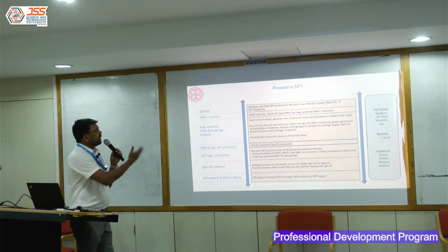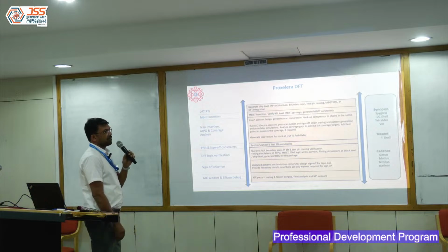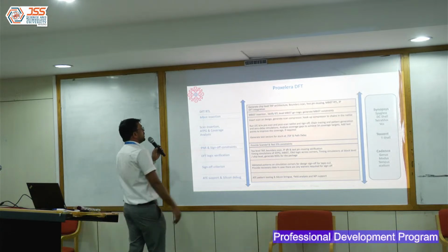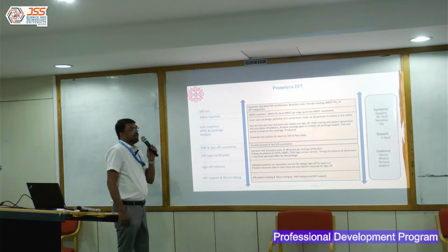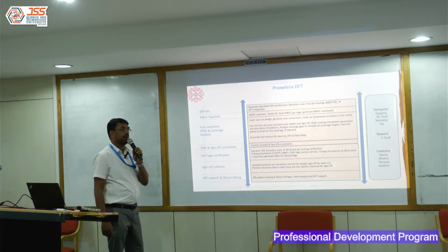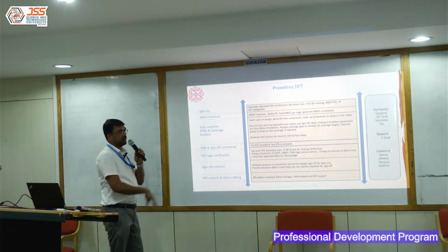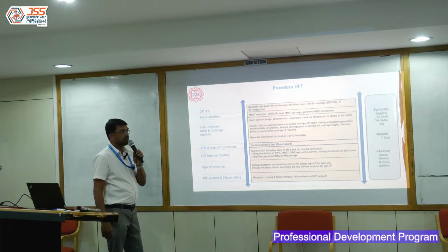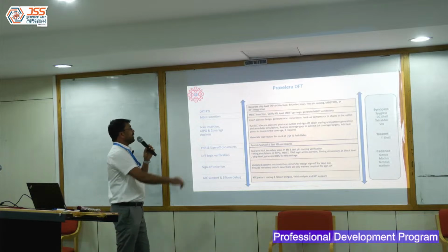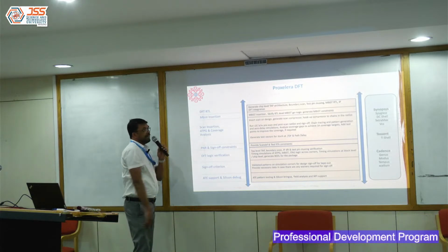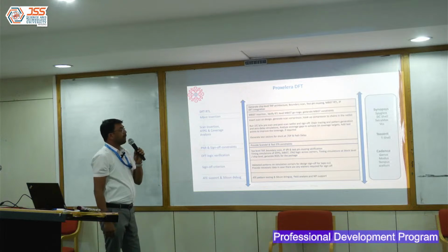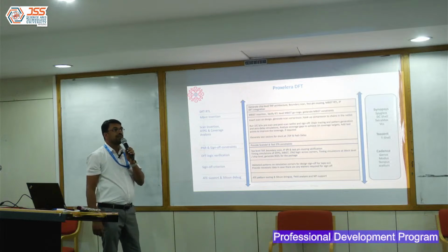So I've just listed a few steps when it comes to DFT. Earlier we used to do DFT at the netlist level, but now technology has advanced. We have the EDA tools also, which are going to help us. So we start DFT right at the RTL level. Most of the MBIST insertion happens at RTL level.